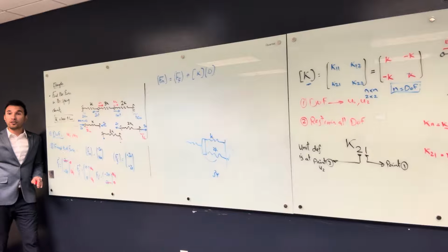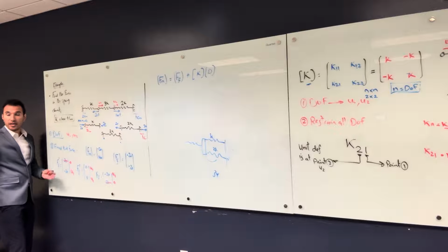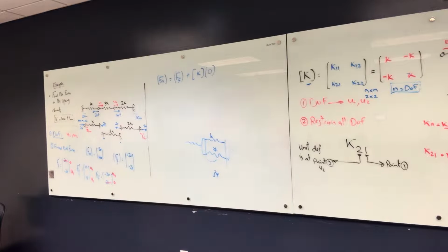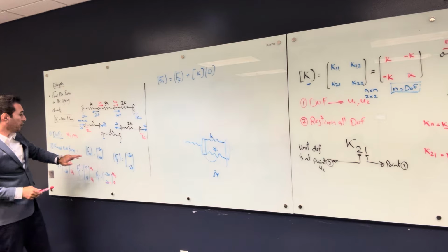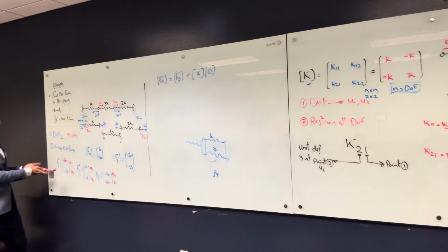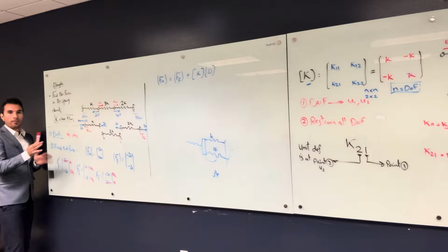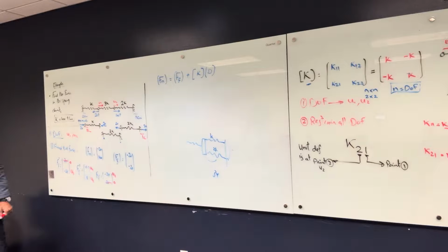So there are different ways to do it. You can do it right away, or you can get each member separately and sum all of them together. Why is F20 low? Because this one doesn't have any displacement. This member, we already included the forces on this member, the 20 and the 100, already in the nodal forces. Okay. Actually, you can make the fixed end forces a nodal force, but you have to opposite the sign, because do you guys remember the action-reaction thing? Yes. So you can do the same thing. But right now, we need everything organized. Okay. With this, let's move to the next step.